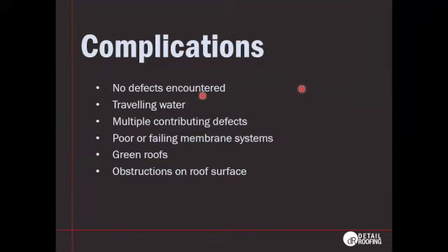Traveling water, again, is a very big one. Multiple contributing defects. So again, this is when we complete an investigation and repair, and then it continues to leak after the fact. Multiple contributing defects can be a result of traveling water. It can be poor or failing membrane systems. It can just be damages present in multiple areas.